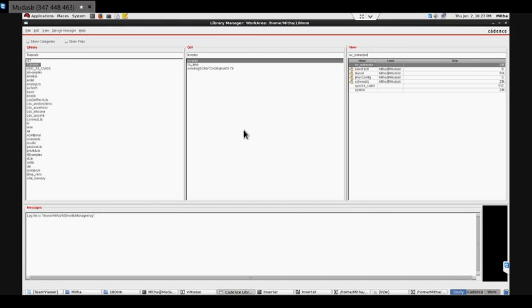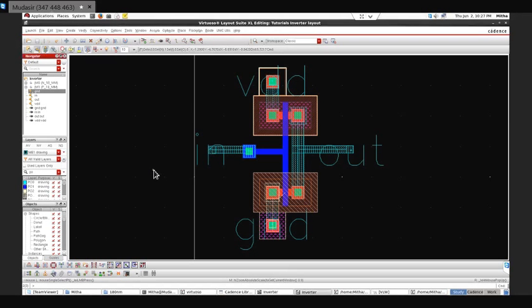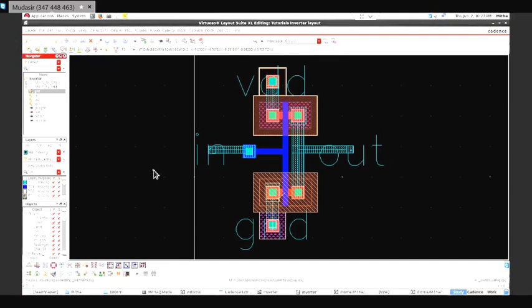So up till now what I have done, we have created the layout of inverter, we checked the DRC, then we went for LVS. Once everything was passed, then we went for RC extraction, and I showed you how the different parasitics are present in this. This is only 2 transistors, but when you go for at least 10 transistors, 20 transistors, you can imagine how many parasitics will be there. So there should be one proper technique, like symmetrical techniques, commons, and there are different techniques which we can't properly eliminate, but we can mitigate the number of parasitics.